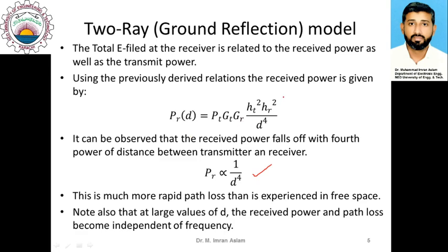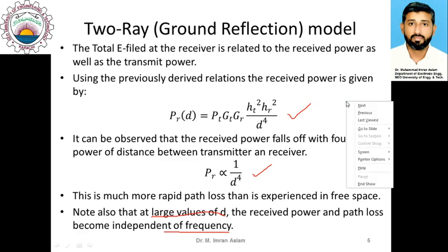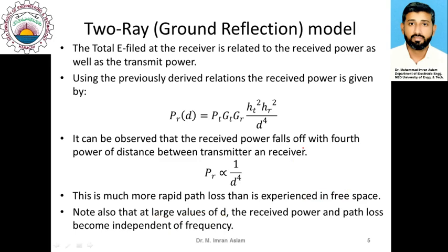Second thing you must note here, that this received power for the large value of d that we have obtained here, this received power is actually independent of the frequency. So if we change the frequency, we would not get a significant change in the received power. So this is another important observation related to this result, that this received power is independent of the frequency of operation of the electromagnetic wave.